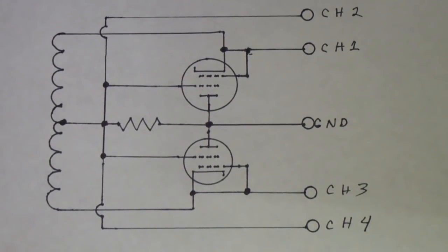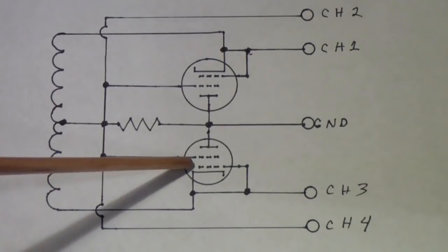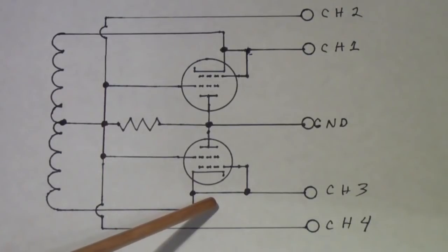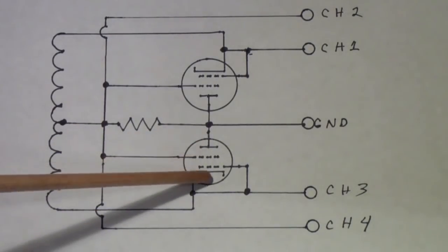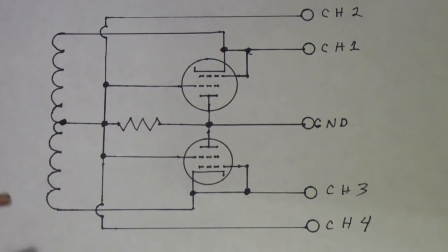So how did I go about doing that? Well, the first thing that I decided is I needed a center tap transformer. And I needed a center tap transformer that could provide the 250 to 300 volts that a good output tube needs to operate correctly, because you don't want to be operating these tubes down in the 80 to 100 volt range, which is where, for example, most tube testers operate them. You want to be operating close to the actual conditions you're going to find in an amplifier.